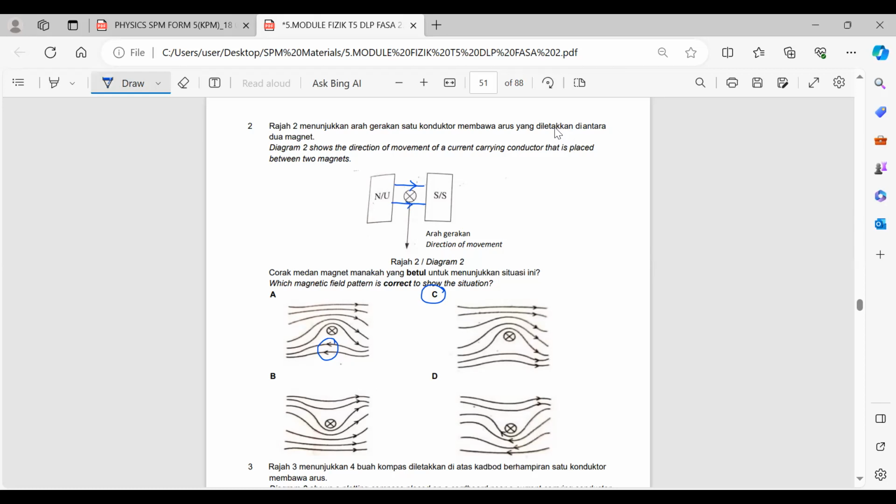And since I know the net force is acting downward, direction of the movement, the force is acting downward, I should have more magnetic field, the catapult field, okay, so more field on top compared to the bottom. So that will produce a net force acting downward. So yes, A and C, you can see more lines above.